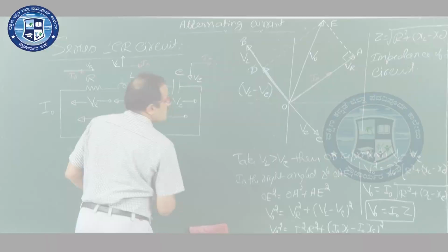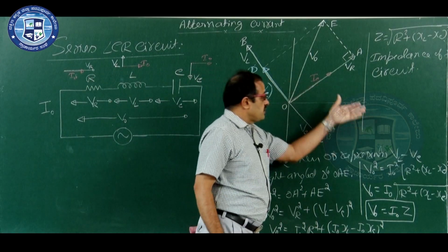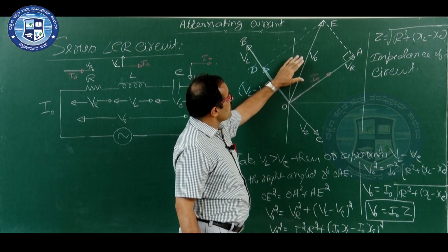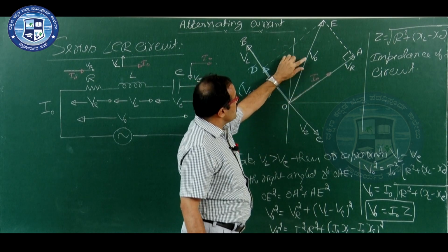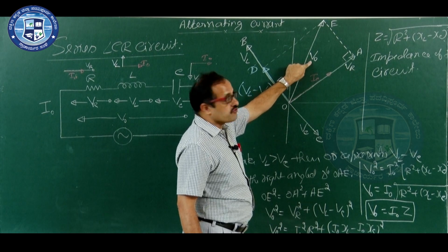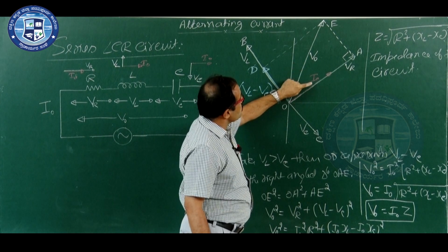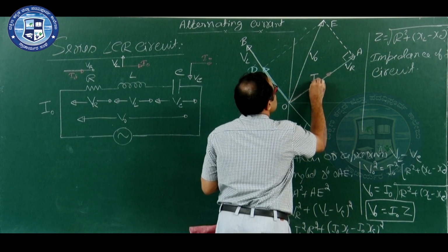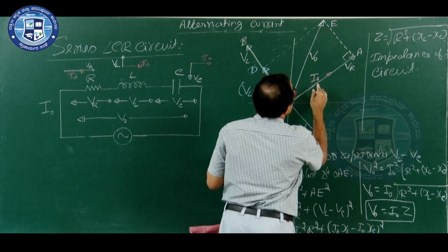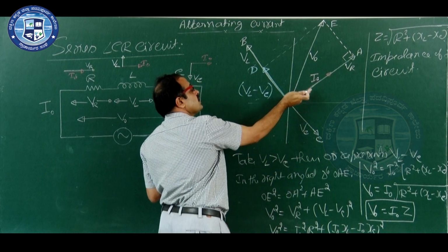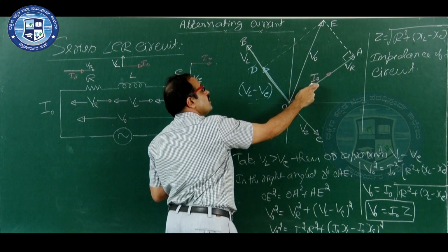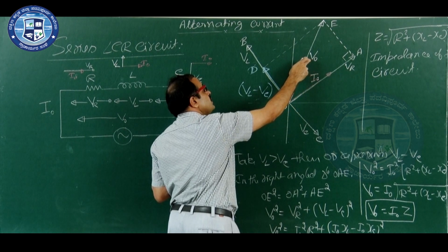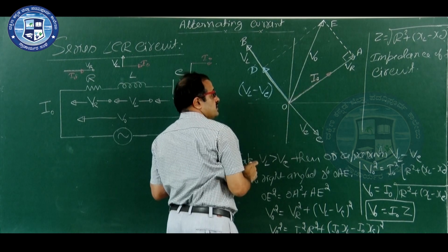Okay. Now, we continue this derivation discussion. Look here, it is very clear now. If you look into this phasor drawing, it is the peak voltage across the circuit V naught. It is the current through the circuit, peak current I naught. Definitely, voltage has a higher phase angle compared to current. Therefore, who is leading? Voltage is leading the current.